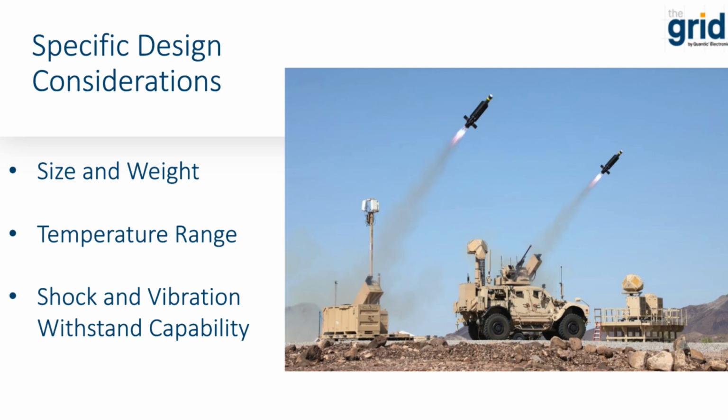Certain capacitor technologies have significant performance variations as the application's ambient temperature changes. For example, some capacitors have much lower capacitance ratings at cold temperatures, losing half or more of their rated room temperature capacitance at extremely low temperatures, which are commonly seen in avionics or space-based applications. Now, other capacitors, such as multi-layer polymer film capacitors made by Quantic Pactron, have very stable performance across temperature ranges due to their unique construction and materials.